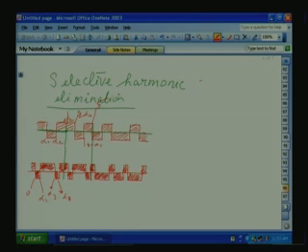If you see the figure here, the two waveforms are given. In the first waveform, we are introducing the notches at alpha 1 and alpha 2. In the second waveform, we are introducing more notches. From the pi by 2 period, we have the quarter wave symmetry.